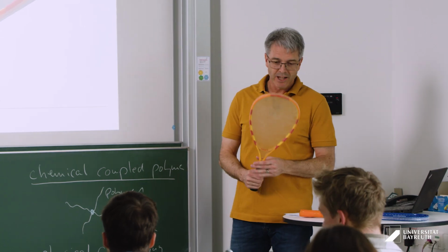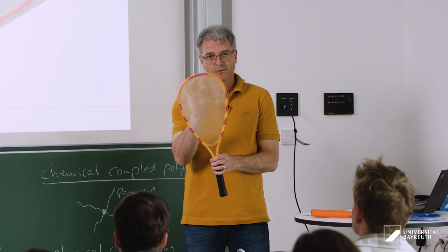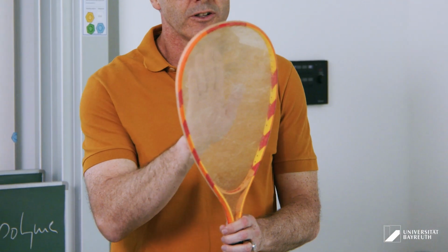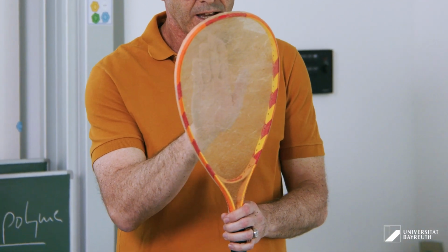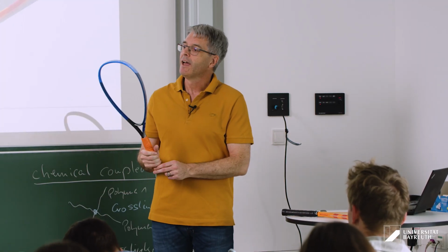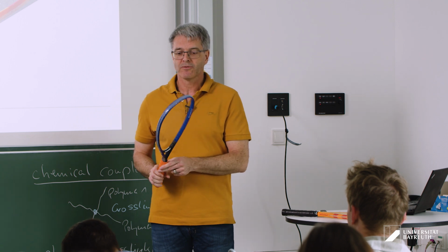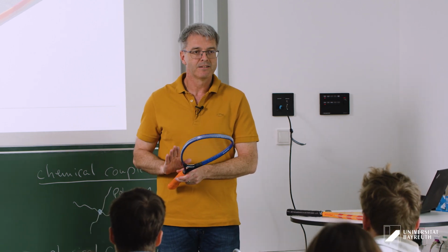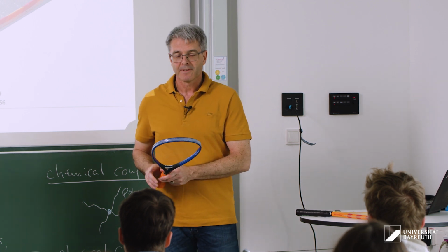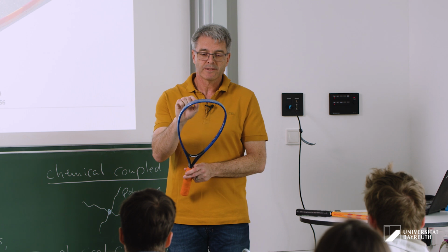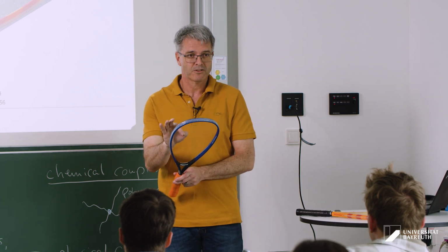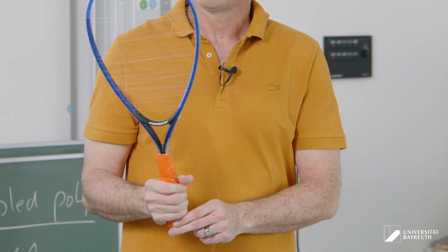Well, it's intriguing because you have to consider that the individual fibers here are 5 micrometers thin. 5 micrometers thin. If you try to do this with steel, it's like that. It took us quite some time to find a company to make thin steel fibers. I do not want to touch this because it will break. That's the intriguing point. So the thinnest steel fibers we can make, to have a direct comparison, are 17 micrometers. So they're roughly 3 times thicker.